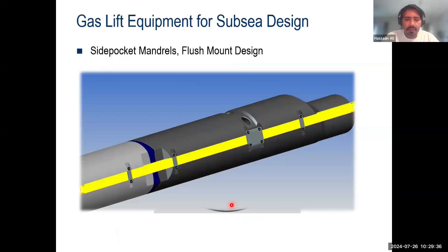For the subsea and deep sea applications, there are other considerations as well. For the subsea wells, there is a lot of monitoring in terms of production, temperatures, and pressures. Usually for that, we have to run cables all the way from the top to the bottom of the well. These cables actually have to pass through the tubing as well as the gas lift mandrel, to protect that cable. Usually they are in the form of what we call a flat pack. So it's like all of the cables bundled in an armor, and that cable has to be secured around the gas lift valve. So for subsea and deep sea applications, we have these special channels that are machined inside the gas lift mandrel so that we can actually deploy the cable through that channel, and then it is secured through these lock screws and lock plates.